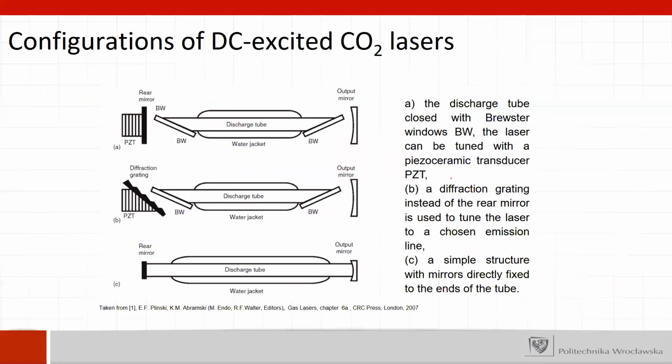CO2 gas lasers can be excited either with DC voltage, but they can also be excited with high frequency excitation, so RF excited. So then we have the plus minus, right, excitation. This can induce pulse operation of the CO2 laser, and we can obtain a lot of power.